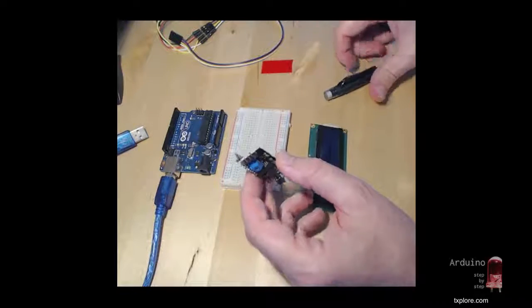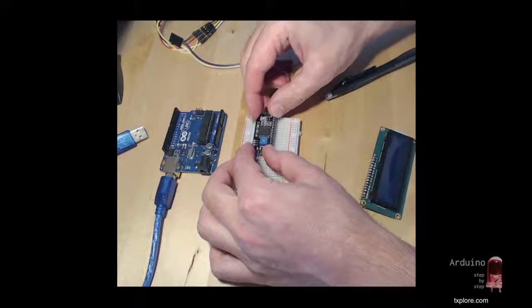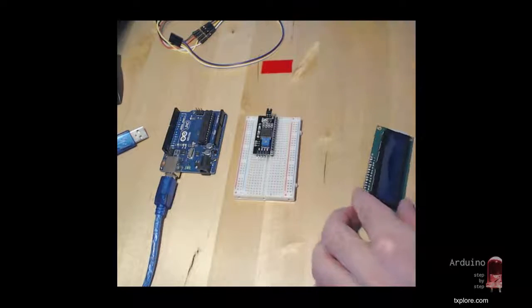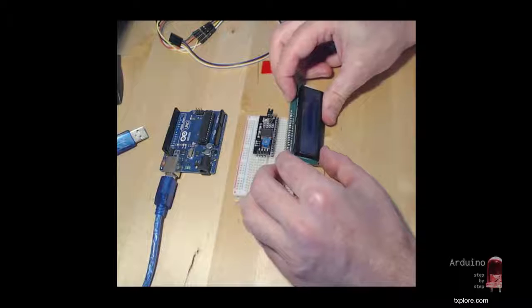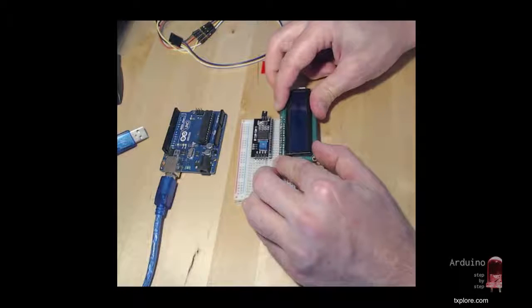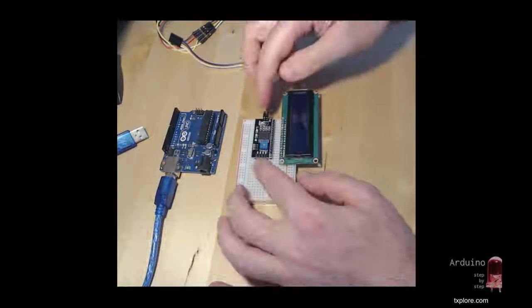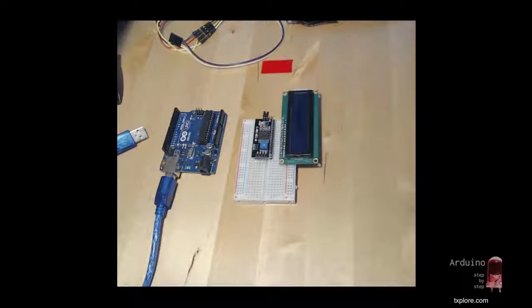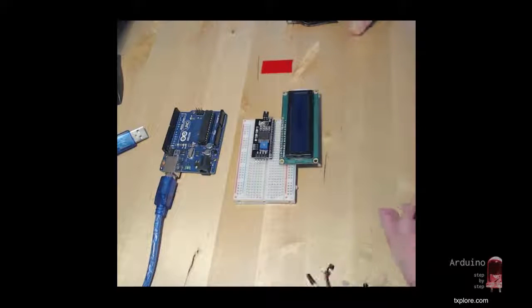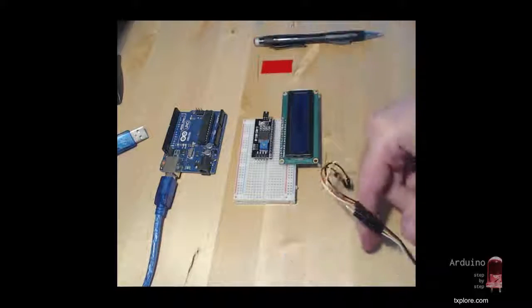Wiring is very, very simple, so let's go ahead and do that. I'm going to plug the adapter here and the LCD screen here, so that there is a nice one-to-one correspondence between these 2 pins. Oh, by the way, when you receive the adapter from eBay, it will not have headers on, so you're going to have to solder this and that row of headers.